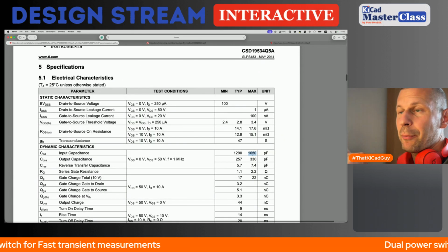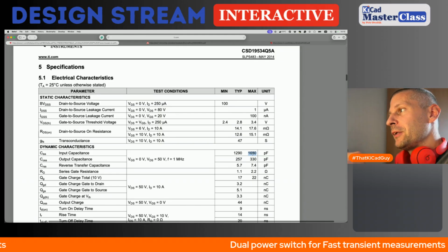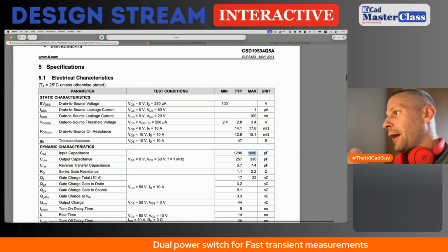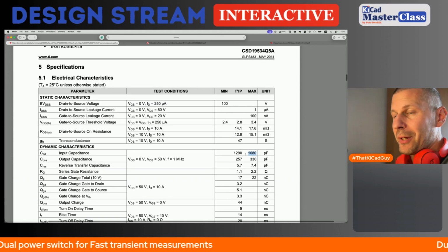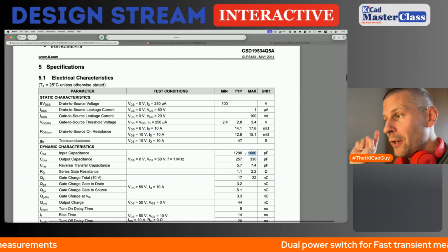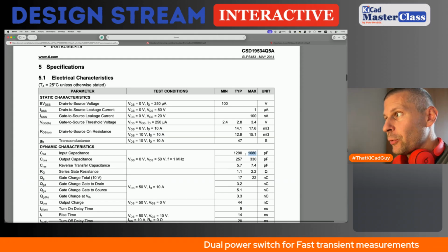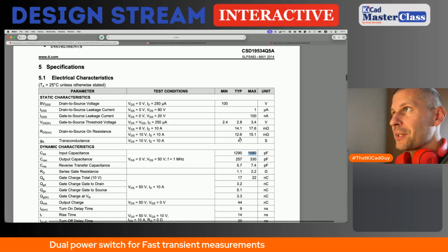It means its capacitance between the gate and the source electrode of the MOSFET. And we need to charge and recharge this capacity as fast as possible. Plus, I want to use 2 MOSFETs in parallel. So it means there will be more than 3 nanofarads of input capacitance.